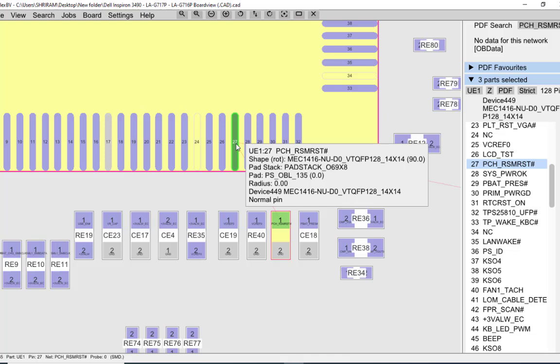But to generate these two signals, the CPU needs something. So see what the CPU needs. The CPU first needs power, that is called VCC DSW. That VCC DSW is a power to the CPU, and this signal generates the 3.3 volt section. The 3.3 volt section has two outputs. One is the linear, called the VL voltage, and the other is the always, a buck converter that turns on. That buck converter voltage goes to the CPU, and the linear voltage goes to the SIO. Okay, so the CPU needs power.